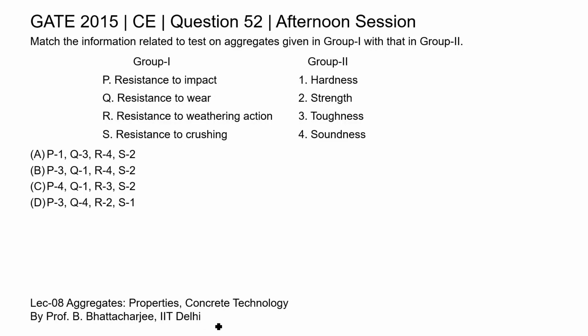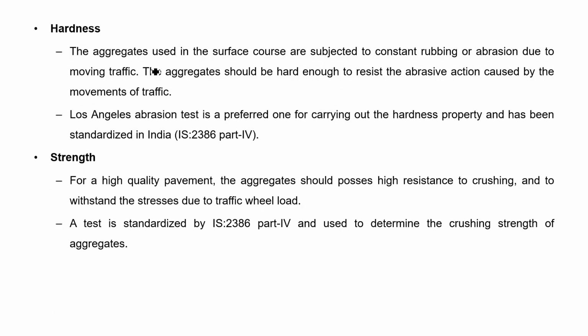So, if we recall hardness, the aggregates used in the surface course are subjected to constant rubbing or abrasion or wearing due to moving traffic. So, the aggregate which is being used in the surface course of the road should be hard enough to resist the abrasive action caused by the movement of traffic.